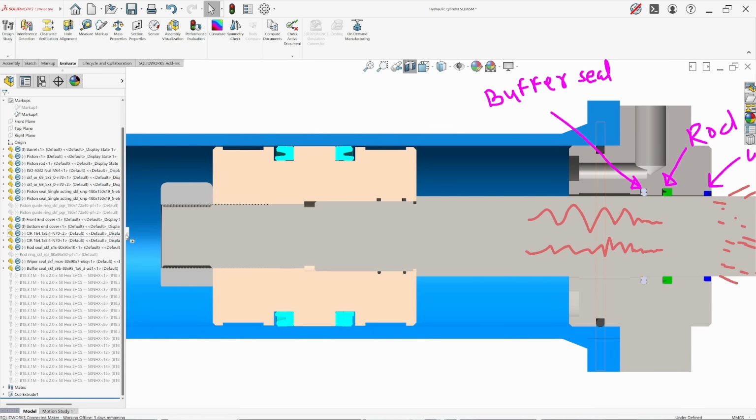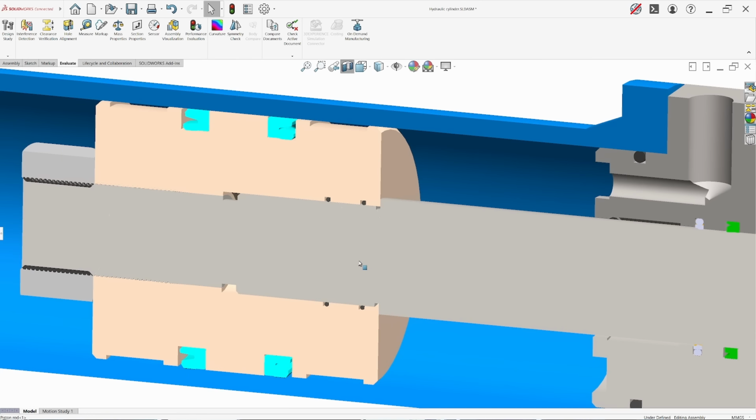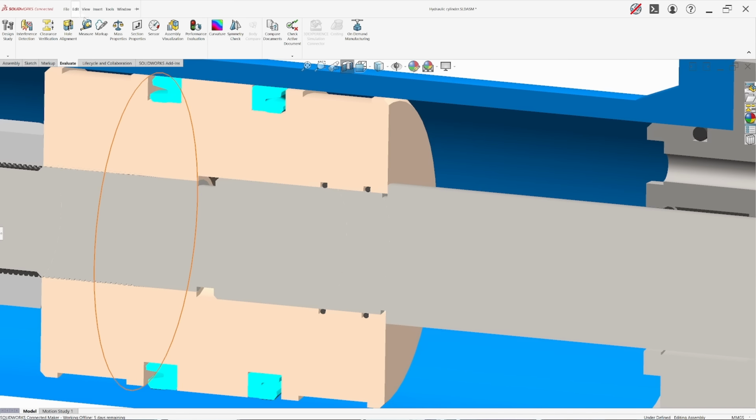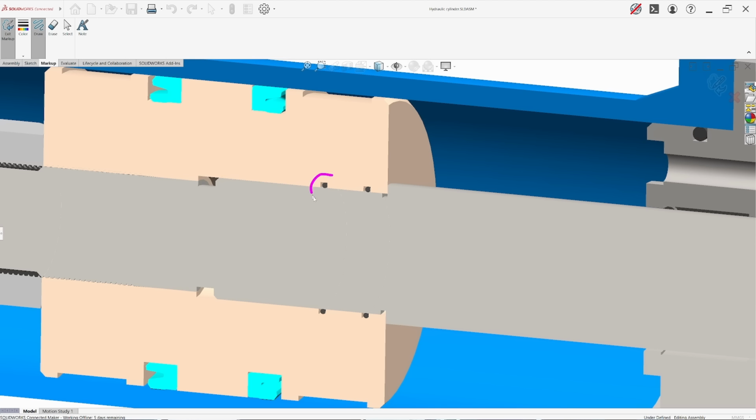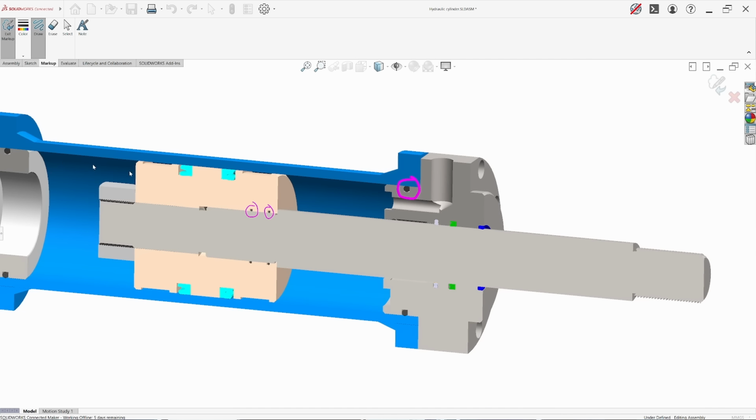Now, apart from all these dynamic seals, we also need static seals at all the fixed connections. The most common static seals are between the piston housing and the piston rod, and between the head of the cylinder and the cylinder bore tube.